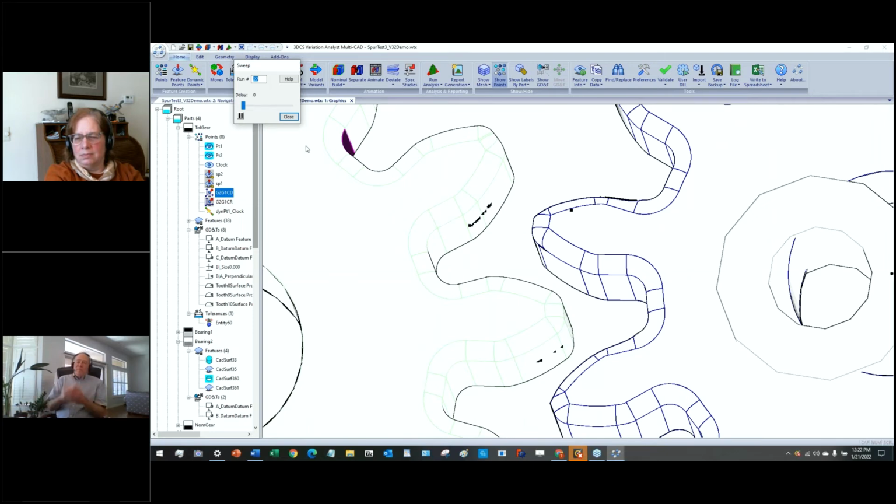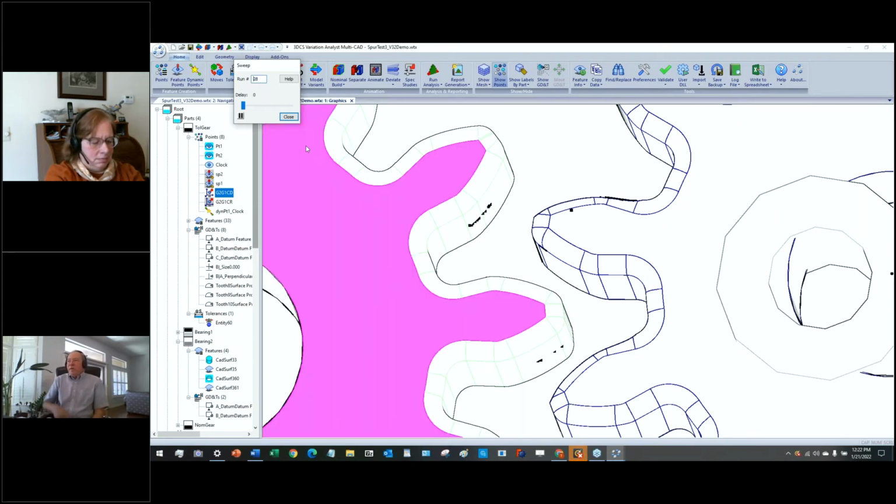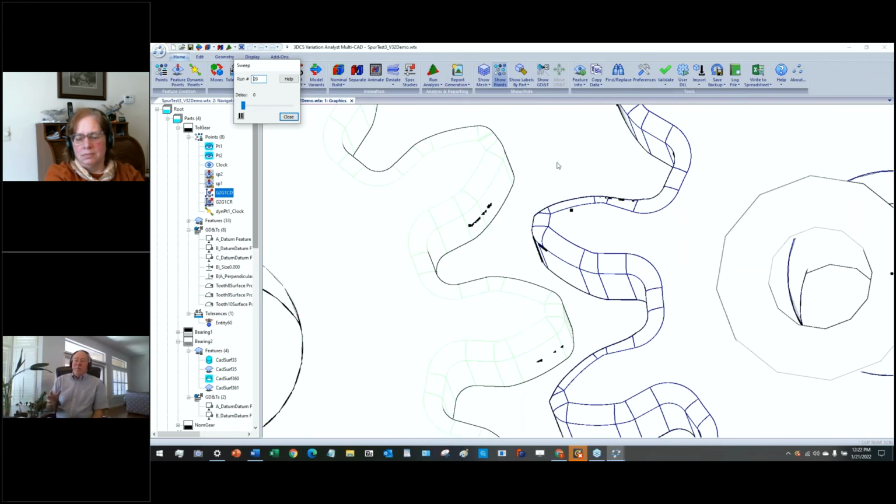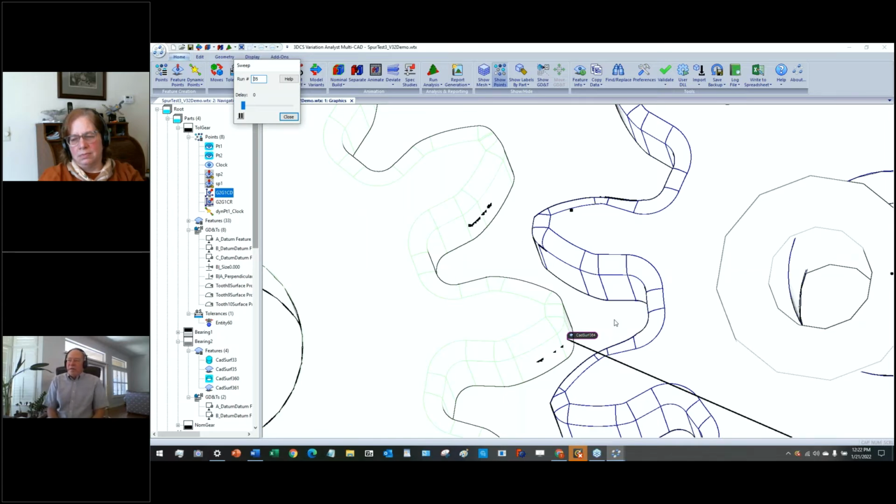So you let this run, and it runs for a while, and you can come back and check it and make sure that there's a standard pattern for the set of gears that they're expecting, and make sure the standard pattern matches. Now, one of the things you might be concerned about is this point at the tip. That's right at the tip of the gears. So you want to make sure that that's not where the gear is putting the most force. And so that would be a concern with this particular gear set.